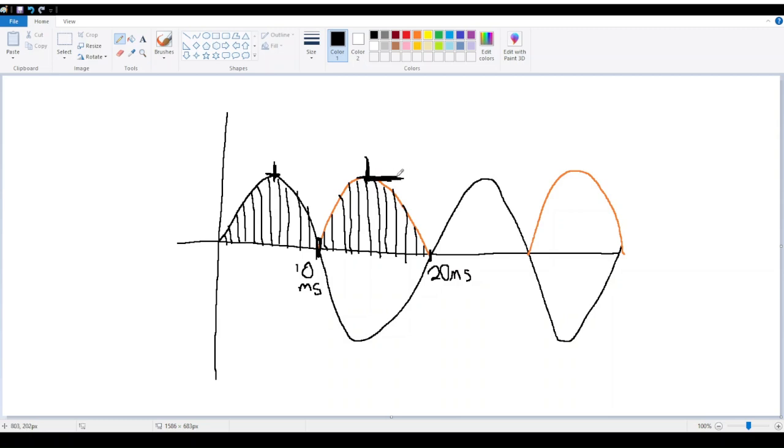So in this case, our desired reference peak is 325.269. This is really bad, but that's basically 230 V RMS. So this 230 VRMS is just an example, but essentially that will give us a peak of 325.269, and we're basically just taking the sine and multiplying it by that.